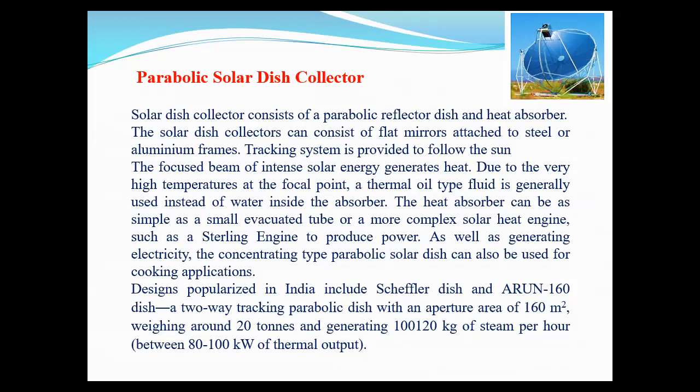So all radiation falling on this collector is reflected at the single point where the receiver is located. And so this collector is called a point focus collector. So solar radiation falls on this large dish and gets reflected on the receiver. And in the receiver, we have oil, working fluid, flowing, which takes that heat.